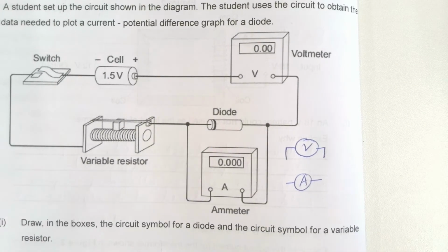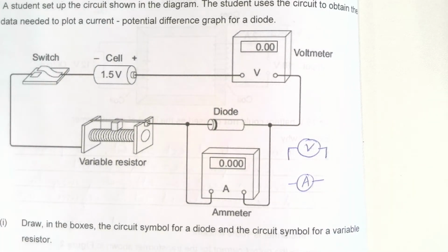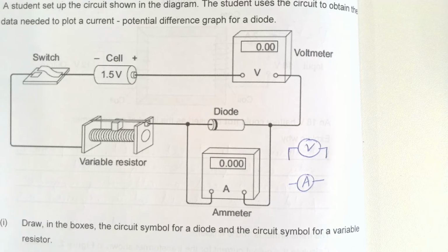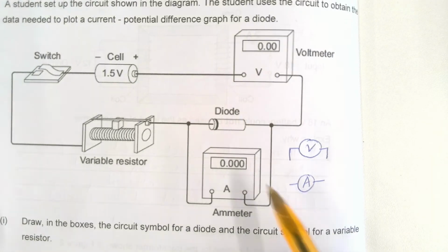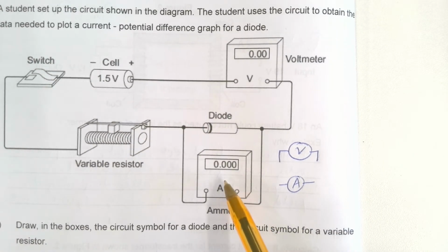to let everything through them with minimal impact on the current itself. It wants to measure the current without really stopping the current. So it's got a very, very low resistance indeed. It's like trying to measure the current in a river. There's no point building a dam to measure the current because you'll stop the current. So you want something very, very low impact. So here the ammeter's got incredibly low resistance.